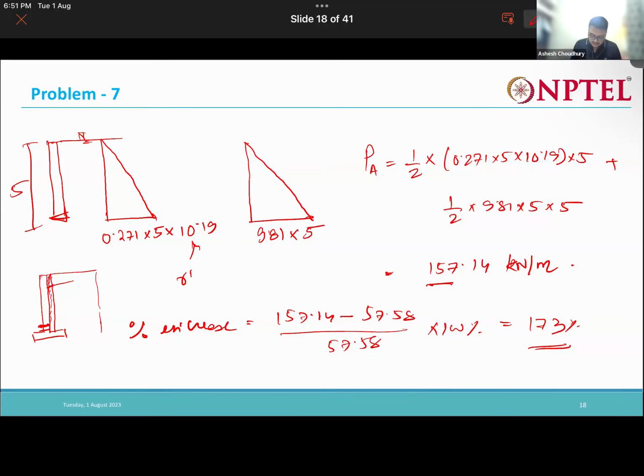So what will happen is that this geotextile material which we will be placing here will allow the water to flow from this soil material to the geotextile, but it won't allow the loss of the soil grains. It will just allow the water to pass through it, percolate through it, and get drained out through the weep hole, right? So it will be acting as a drainage material.